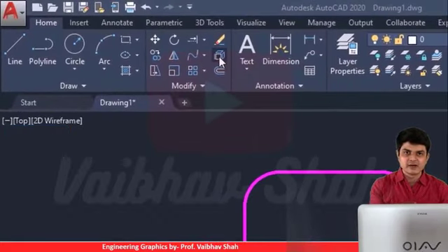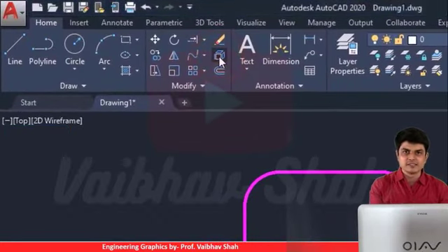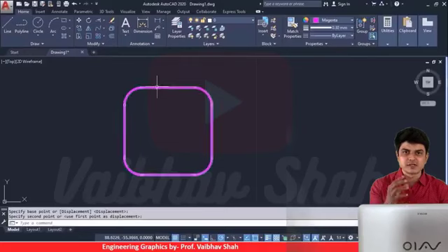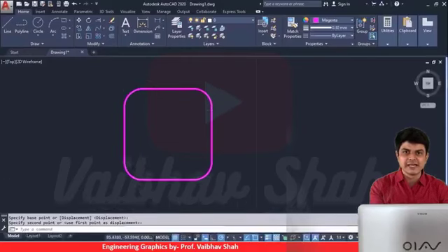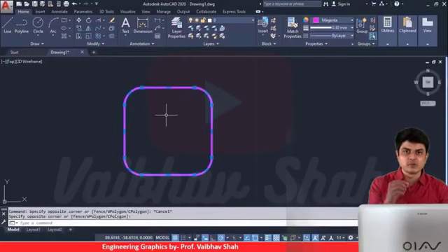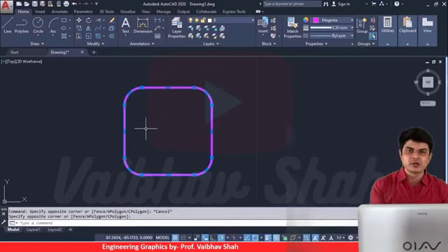So this is your polyline object, and when we press the explode, it will just separate out each of the parts of your component. So this is your solid object, a closed object made by a single solid line. When you select the object, it will show as one entity. But when you press the explode command, it will explode each portion and separate each of the parts or elements of that particular portion.